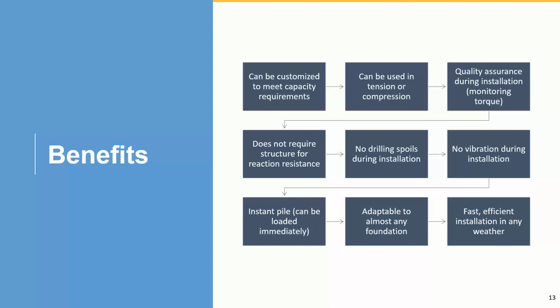We didn't get torque. We were trying to get 20,000 foot-pound torque. We kept going based on the soil report. We should have hit torque around maybe 57 or 60 feet. But for some reason, we put in God knows how many feet, and we didn't get torque. So we decided to grout it to get the capacity.